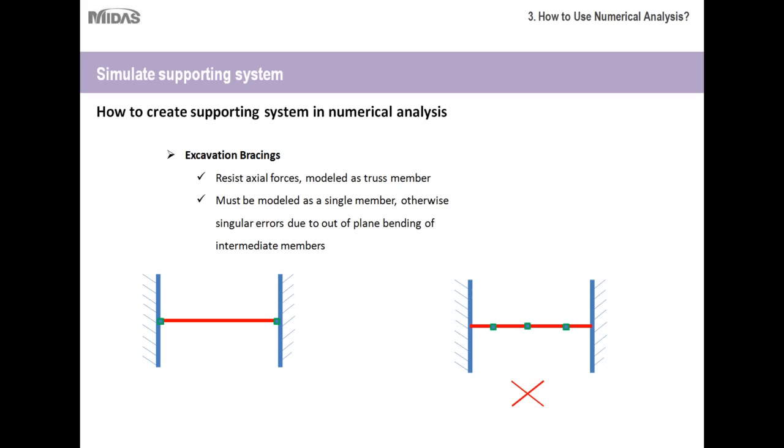So it's actually much easier to model bracings correctly as opposed to incorrectly. It's easier just to draw your lines from one node to the other. Modeling it incorrectly takes more effort. So that's just another thing to remember before you run your analysis. Just make sure that all of your bracings are modeled such that there are no nodes in between the tips or the ends.